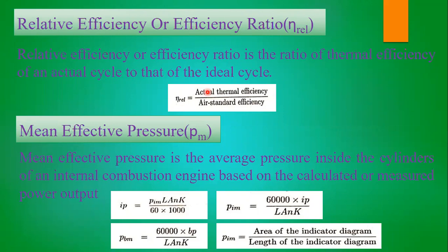Okay, next, charge efficiency. What is charge here? Charge means nothing but the air-fuel mixture. In SI engines, or in two-stroke engines, we talk about this charge, the air-fuel mixture. The amount of charge we take in should be as much as possible. If we have taken in more air-fuel mixture, then the charge efficiency is going to be higher. It is the amount of fuel taken relative to the ideal amount.